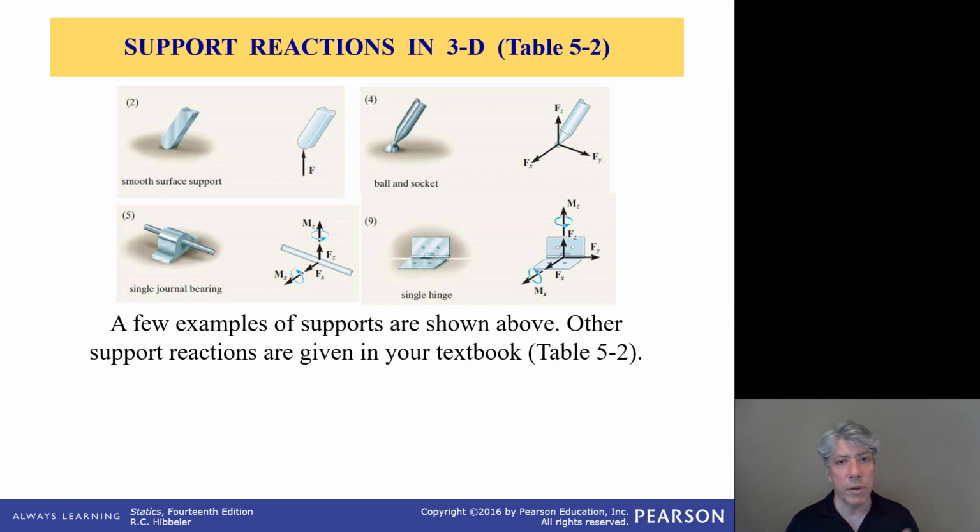And if it doesn't work out, if the structure is not stable, then change the design so that it is, rather than relying on a bearing like this to support a moment in either the X or the Z direction as shown there. So there's a little bit of nuance with this. You really have to know what you're doing with it, and you'll get used to it.